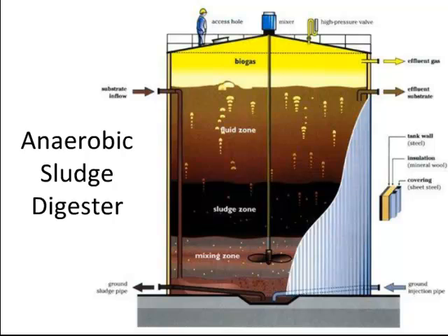So these anaerobic digesters digest down the sludge until it can no longer produce any methane. At that point, it's moved into a second digester where the sludge sits and is given time to digest even more. Once it's broken down some more, the sludge has to be removed. And there's really three fates that can happen to that sludge. Number one, it is taken, mixed with a polymer, so it comes out looking a bit like Play-Doh, and then is carried and put in a landfill.